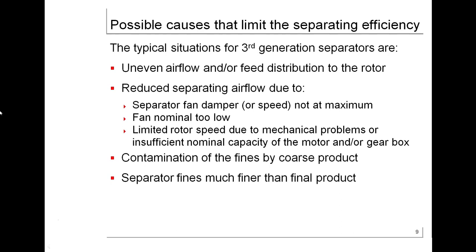Reduced separating airflow due to the separator fan damper not at maximum, fan nominal too low, limited rotor speed due to mechanical problems, or insufficient nominal capacity of the motor or gearbox. Contamination of the fines by coarse product. Separator fines much finer than final product.